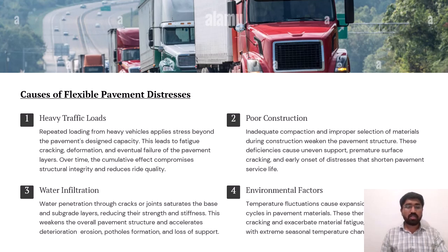Causes of flexible pavement distresses: heavy traffic loads, poor construction, water infiltration, and environmental factors. Heavy traffic loads: repeated loading from heavy vehicles applies stress beyond the pavement's design capacity. This leads to fatigue cracking, deformation, and eventually failure of the pavement layers. Over time, the cumulative effect compromises structural integrity and reduces ride quality.